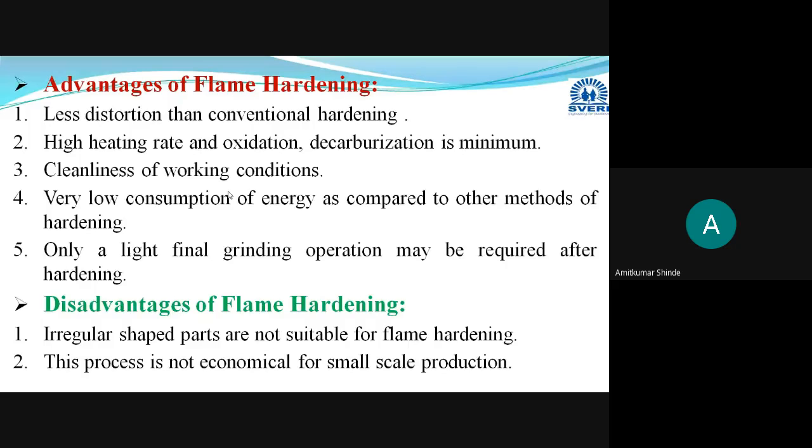Then what are the disadvantages of the flame hardening process? Whenever an irregular shaped component is there, you cannot do the flame hardening process. These are not suitable. You can do it, but proper hardening is not achieved, because you have to take that oxyacetylene flame on that spot.